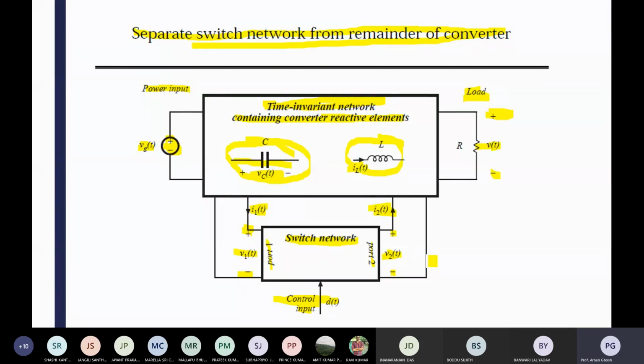So you can get the transfer function after calculating all those values in the M file, and you have the final transfer function of your converter plant. Now you can use a model MDL file.